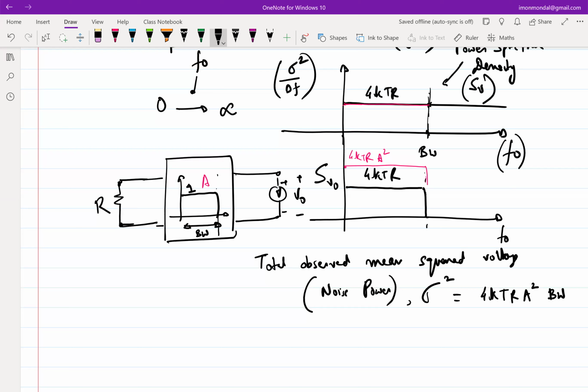What can you comment on the effect in the presence of noise? Noise will be higher, right? Because you cannot get rid of thermal noise. It's there. The moment you have a resistor, you have thermal noise. And just like you saw, when we are receiving something through the antenna, it is also kind of a resistor, right? So it's a 50 ohm resistor.